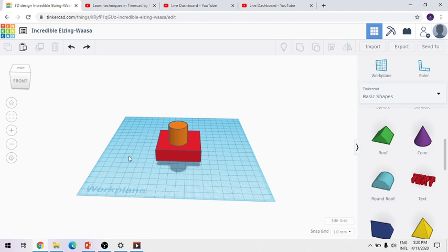Now if I want to place a ruler, there is one option, C, ruler, and if I press R, it will set the ruler here. Then I can change the dimensions. This ruler is used for placing the object on that grid, because whenever we print any object on a 3D printer, we need to set the dimensions initially, then only our object will be in the right direction.